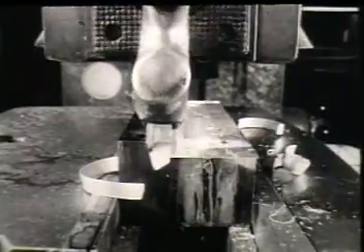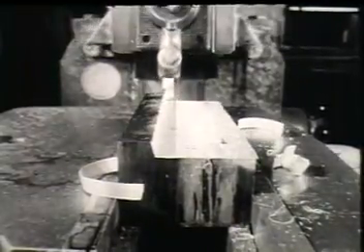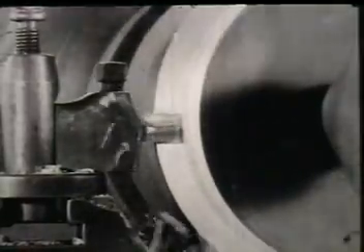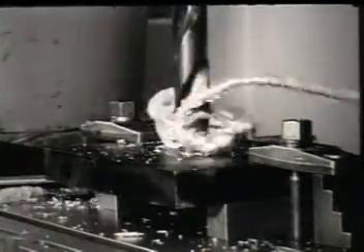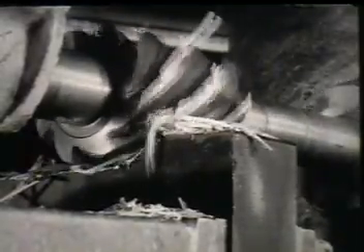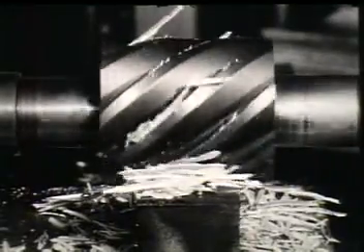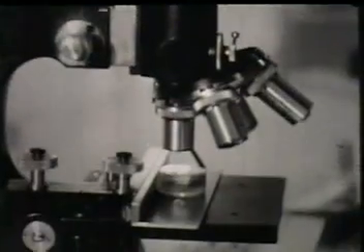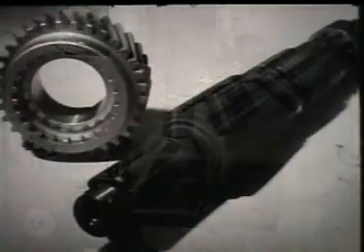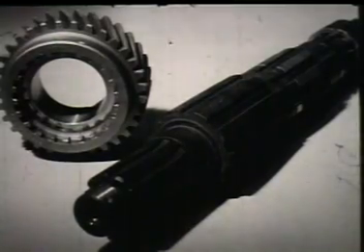A knowledge of the chip formation process is necessary to predict the properties of a part which has been machined, as well as how the part will perform in use later. The surface finish obtained is dependent upon the microstructures in the material, and the surface hardness is equivalent to that hardness obtained by cold working the part to its maximum. Both the finish and the hardness of a machined surface influence the in-service performance of a structural part.